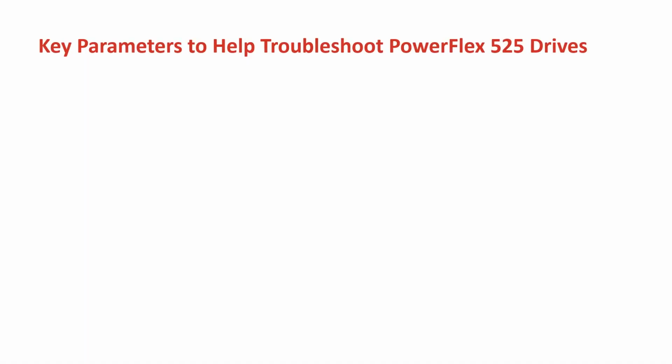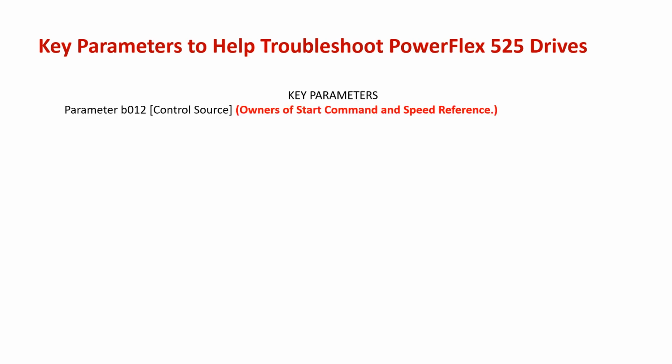In this video, we'll be talking about PowerFlex 525 drives and parameters to help troubleshoot them. Key parameters to help troubleshooting a PowerFlex 525 drive. First one would be parameter 12, control source. This shows us the owners of the start command and the speed reference.